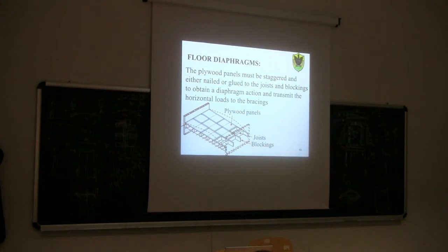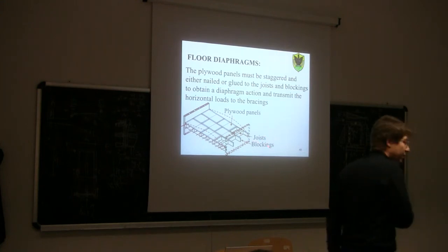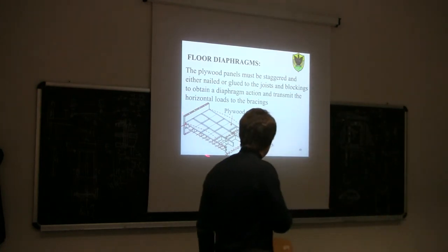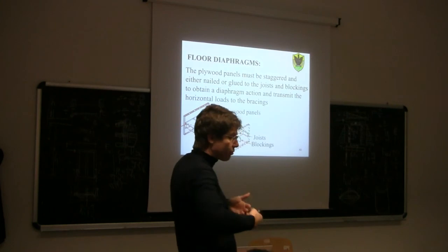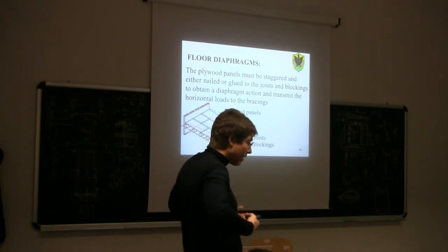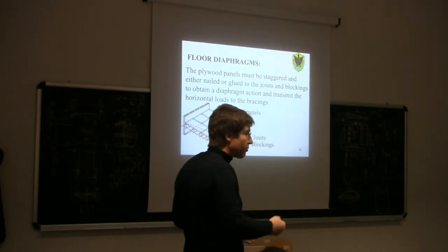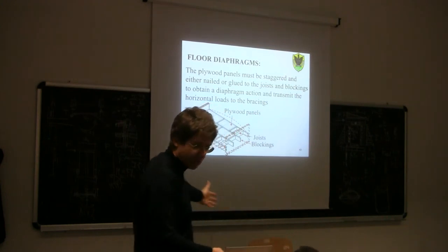Probably you remember when you do your design, you didn't check the floor for in-plane forces, you just check the frame, you just check the floor for the vertical floor. That's it. Here instead, since this is not monolithic, here we need also to design the floor and the different components in order to be able to transfer the lateral load to the bracing system. So you need to do more checks in this case, okay?